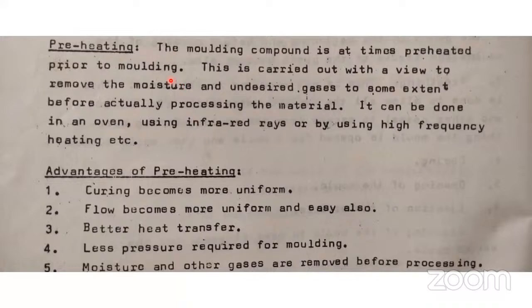आपको preheat देना पड़ता है, but preheat कितना देने का? Not 140 or 194. No, preheat maybe up to 80, 70 like that. Not very high. If you give very high heat, the polymer starts to polymerize in the heating only. Therefore, we just want to remove the moisture, and a lot of many advantages are available by preheating